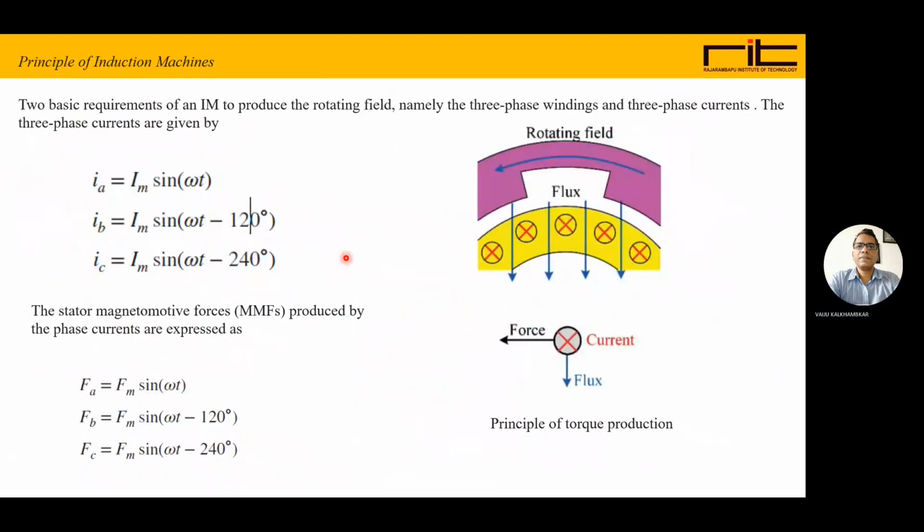and this rotating magnetic field will link to the rotor conductors. Now, there is a stator winding, a three-phase supply is given, and then a rotating magnetic flux will be produced because of this phase difference, and it is revolving at synchronous speed. It may be 1500 rpm, for example.